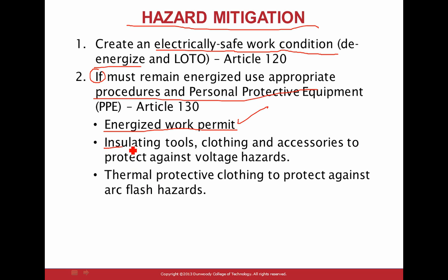And then make sure you're using insulated tools, clothes, and accessories protecting against the hazard of voltage, and thermal protective clothing to protect against arc flash. So then you have to suit up for the appropriate arc flash. Any comments, guys? Any questions?